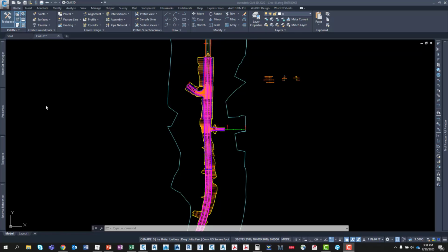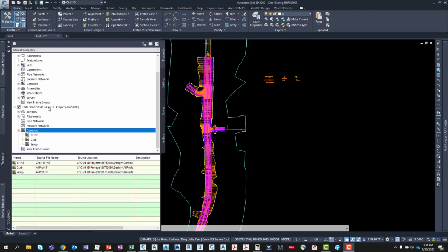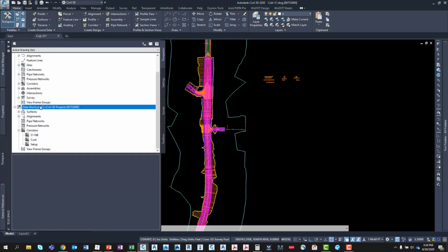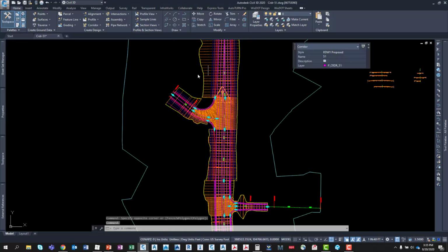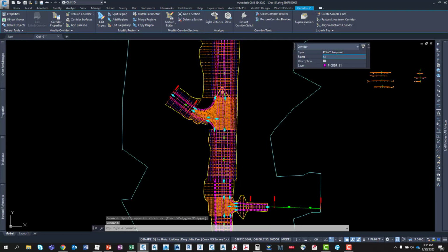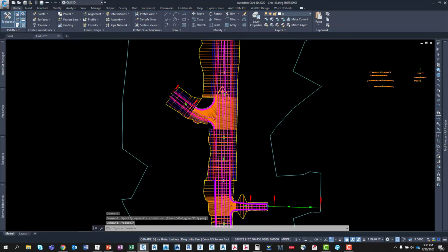So now we'll jump right into Civil 3D and start working at the basics of creating data shortcut references of corridors. We can check my Toolspace Projects and look at the data shortcut menu and see that there are 3 corridors already sitting there. This corridor here in this drawing is named 51, and is not a corridor data reference, or a corridor data shortcut.